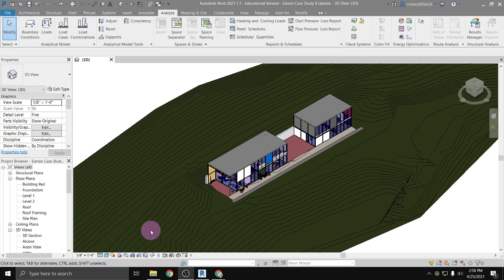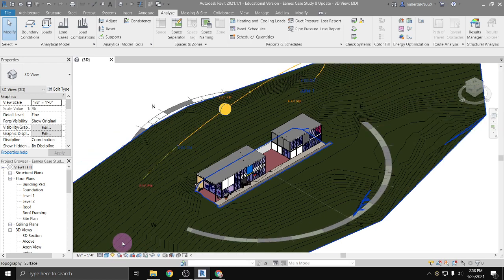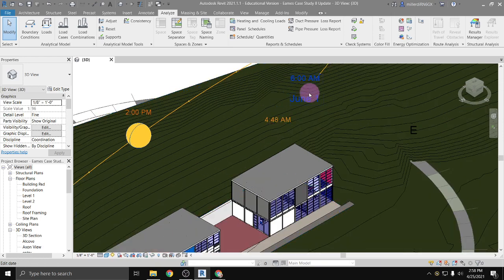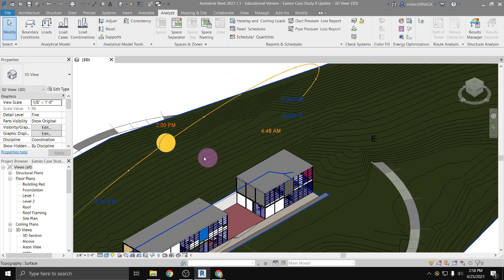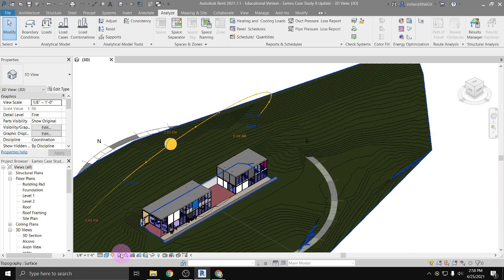But this was part of your Revit project, to look at some of those things regarding the solar analysis. So just to briefly go over them again, you can get to the solar analysis through here, through your sun settings, and I'm just going to turn the sun path on. What this is creating is a little path of what the sun looks like on a single day, June 1st, and how that sun path can follow.